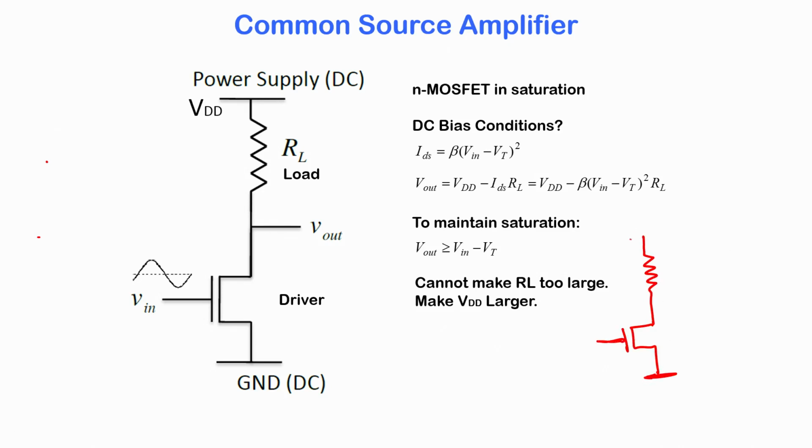So, what we are saying is there is VDD plus small signal VDD. Is there a small signal power? No, this has to be 0. We would like the power to be constant. Okay. So, before I do this, let me just reiterate the point I made. If there is a DC plus AC, AC is all shown in small signal. Okay. So, everywhere you have some DC nodes and AC nodes.